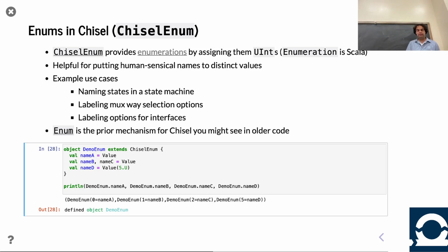And that's one of the things, whenever you have enums, as a hardware designer, a lot of times you don't care what the number value is. The reason I use an enum is to avoid the risk of having magic numbers floating around your code. You have some comparison against 2, comparison against 3, and you have to change it in all places. With an enum, you have a single source of truth. You define the enum in one place. Everyone who uses that enum is then in sync, and when you change the enum, all the users change at the same time, right?